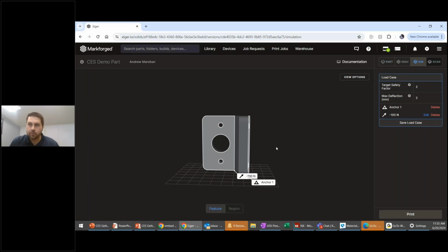Yes and no. One thing to consider is that the longer your part is paused, it does have time to cool. Like anything, when it heats up or cools, it has a coefficient of thermal expansion, so it will shrink a tiny bit. And I say tiny bit because when you go to resume, if it's been more than a couple hours, you will see a very small witness line where the layers below it have cooled and shrunk a tiny bit.